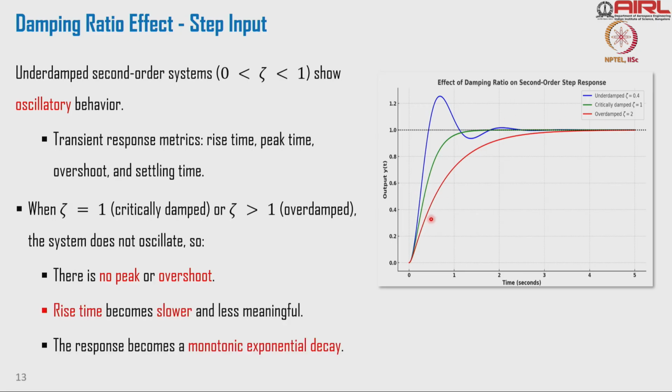But the other thing is how fast it rises to the steady state. If you look at an underdamped system, it rises much faster. The rise to the value slows down when the damping starts increasing. That is another factor we need to remember.